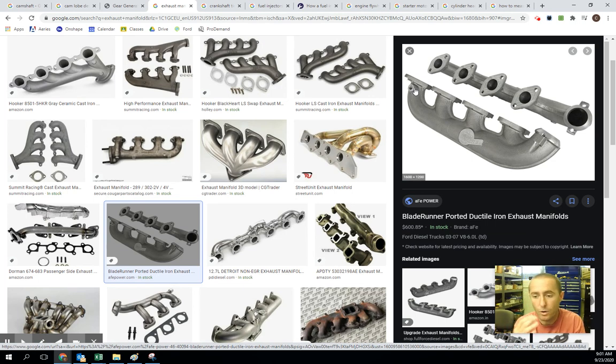We talk about our intake stroke, right? On the intake stroke of our motor, our piston comes down, our valve opens up, and it creates a vacuum within the combustion chamber. It draws air and fuel into that combustion chamber because it creates a low pressure area, and everything else wants to come into that area. Something similar happens with our exhaust manifolds as well. On our exhaust stroke, our exhaust valve opens and our piston comes up and pushes those exhaust gases out down this tube right here.